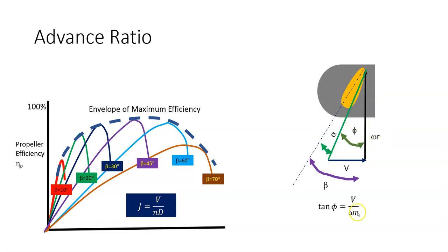And if we look at this omega r, well, omega is the rotational velocity in radians per second, and that's RPM divided by 60 multiplied by 2 pi. So that just becomes radians per second by 2 pi. So if I go omega r, it's n 2 pi by r, and 2r is d. So I get n d pi. So I can put in here n d pi.